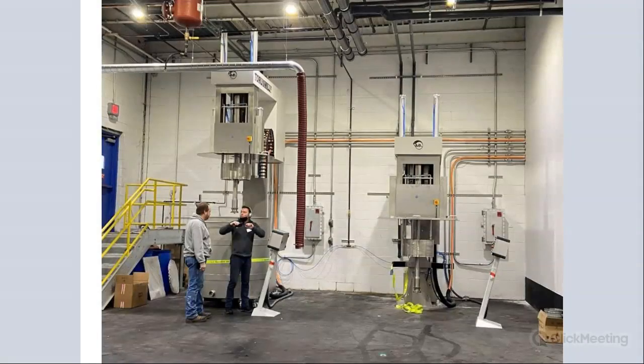Here's an example of two manufacturing grade DisperMats at a pigment dispersion company. Here we have a system called the DisperMat TM, which is the combination. It has a dissolver, with the disc back here, not installed yet, and the basket mill already integrated. The customer does his pre-dispersion in the container, and when he's ready to do the milling, the fine grinding, all he does is push a button on the control panel, the basket gets lowered, and the whole thing turns into a milling system.